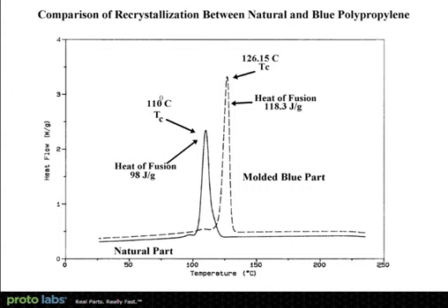We can open the mold a lot quicker because by the time the natural material has started to crystallize, started to solidify, the blue material is already done. So from a cycle time standpoint, this is great news. And we certainly try to capitalize on this. It also has an influence on the way a part shrinks. But the bad news is it also brings with it a sacrifice in performance.